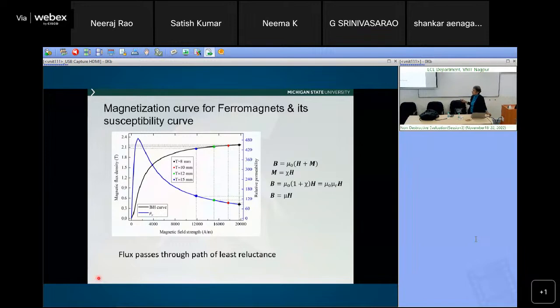Right. So basically, mu is the derivative of B with respect to H, dB by dH. If I look at it as piecewise linear, then I will say it's constant. This is a constant positive slope, and then here it becomes 0 when it's flat. So that is intuitively how it should change, and that's what we're seeing over here. We are taking mu as the derivative of B with respect to H.